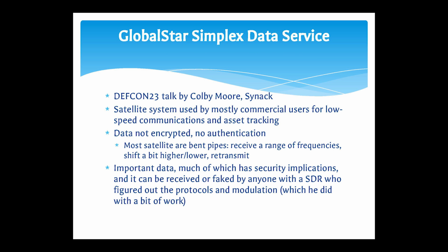There was a DEF CON 23 talk, which I really recommend you look at. Colby Moore found a satellite data system used for tracking assets that did not use data encryption or authentication. It just broadcasts in the clear, and this has been used for 20 years. The data is just broadcast. Anyone with the correct radio, an SDR, can send or receive these signals. And a lot of security processes were put in, assuming that this data was secure, controlled and authenticated, which it's not.